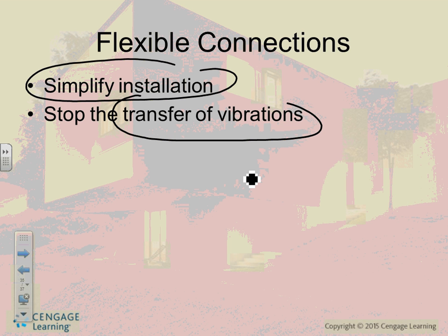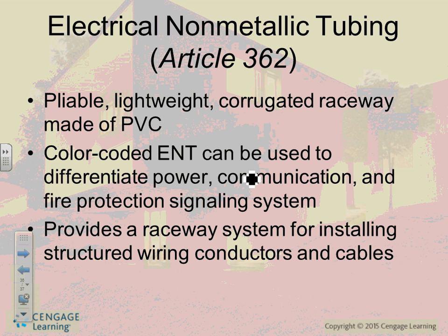It's not approved. So, okay, PVC, gentlemen. You're looking at the PVC right here. What did we say about the PVC? Conduit of choice when you go where? Wet or underground? I like the word wet because what if you are in a car washing machine, car washing a building? Wet, it's not underground. If you guys ever look at the wiring methods in a car washing area, you see a lot of PVC in it. Why? Corrosion. Conduit of choice for corrosion.